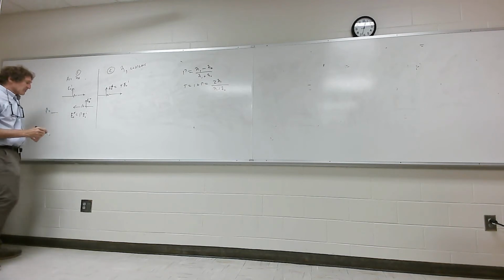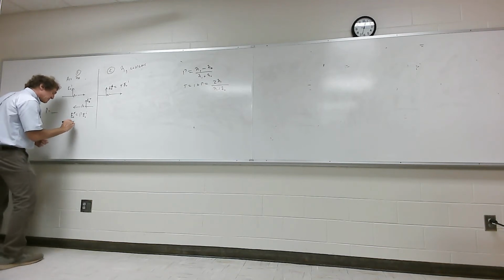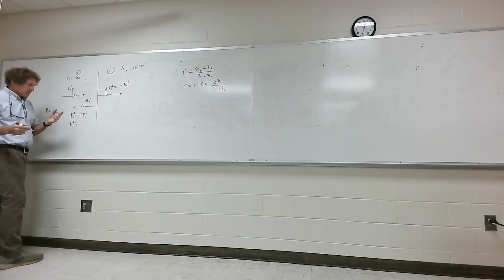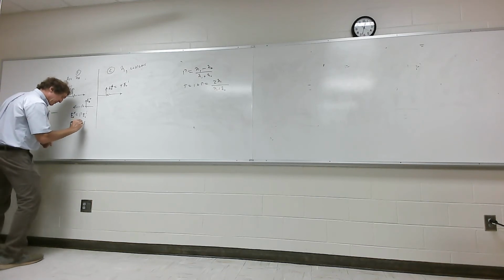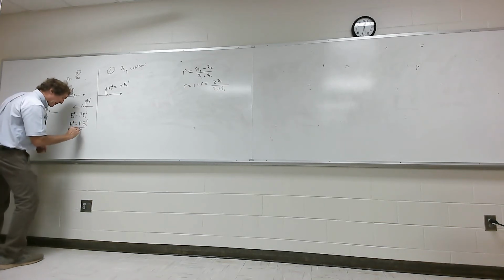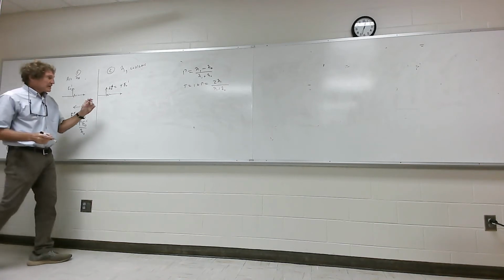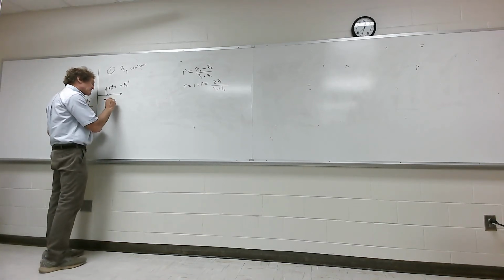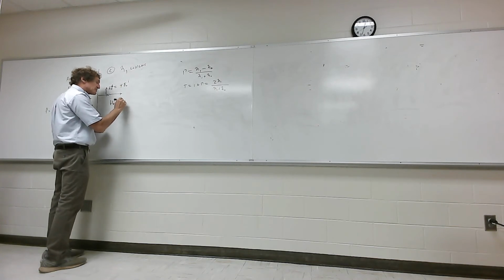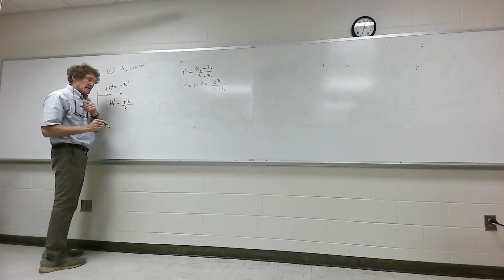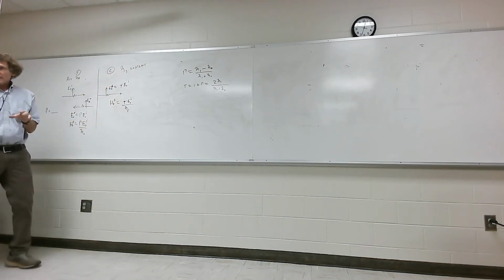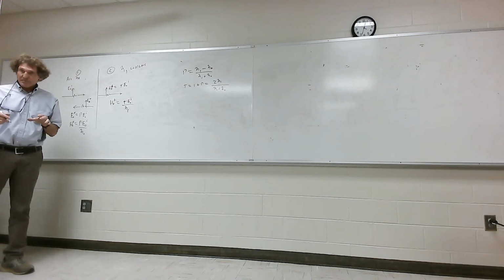Now, if we wanted the H field here, what would the H field reflected be? It would be the E field that's reflected, divided by, in magnitude, I'm just worried about magnitude, eta 0 here. Y'all agree with that? That's just the magnitude I'm showing you. The direction is obviously going the opposite direction. Over here, there's where mistakes are made. The H field is going to be that, but now it's over eta 1, the impedance of that medium. It's different. Y'all with me?